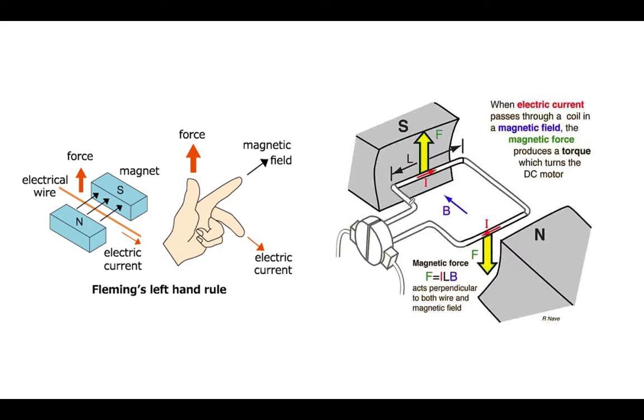It is wound over a shaft to rotate, and at the end of the coil it will have copper plates which will be rotating along with the current conducting coil, and they will be touched with the carbon brushes. These carbon brushes will make contact with these copper plates, so that the supply is applied to this coil constantly, even though these current conducting wires are rotating. So if this current conducting wire is rotating, they need a constant supply so that they keep on rotating.